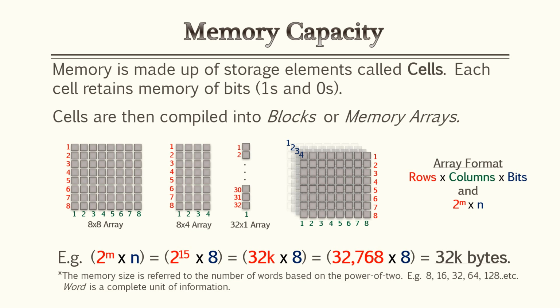Now this is also going to lead to the common term you may hear for memory size. You're not going to hear 32,768 bits or bytes. You're going to hear 32K, 64K, 128K bytes. That's because the memory size is referred to the number of words based on a power of 2.